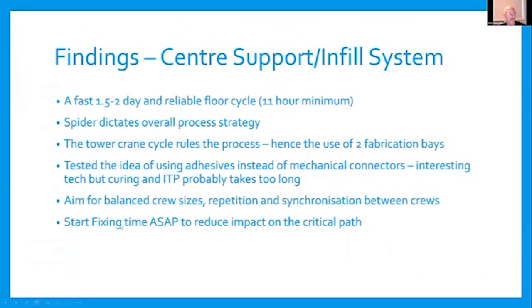So coming to a sort of conclusion and findings: a pretty fast, 1.5 to 2 day, and reliable floor cycle. Our actual bar chart suggests about 11 hours was the minimum. The spider dictated the overall process strategy. Tower crane cycle rules the process, and that's why we use 2 fabrication bays.